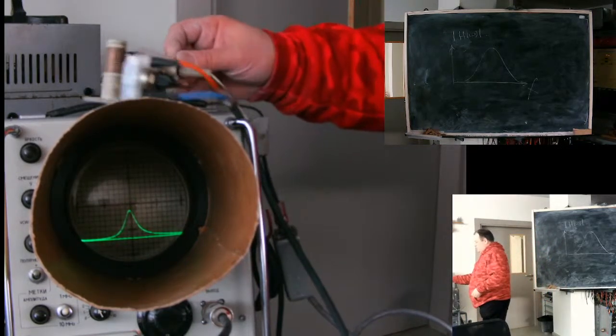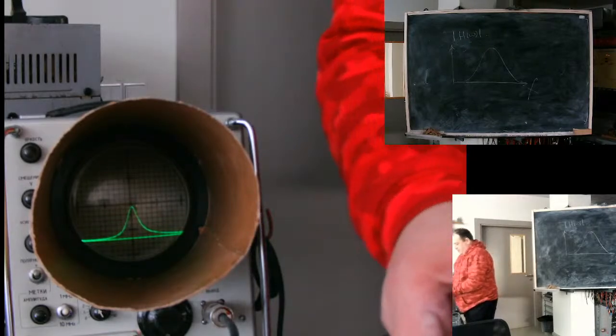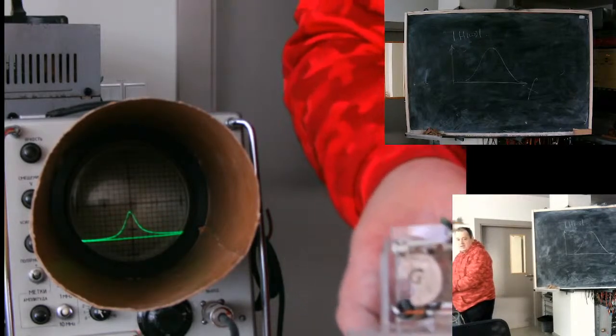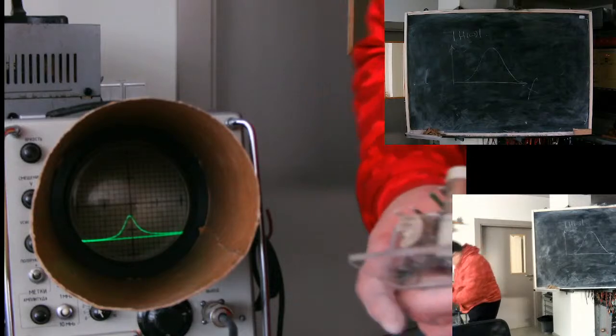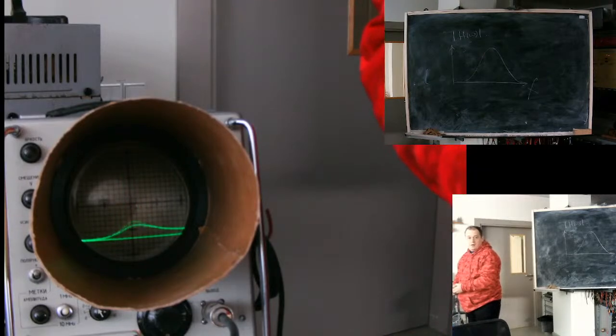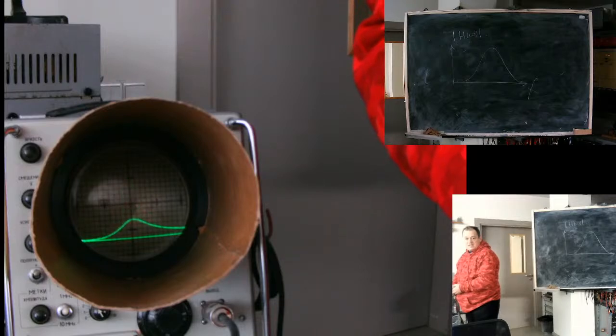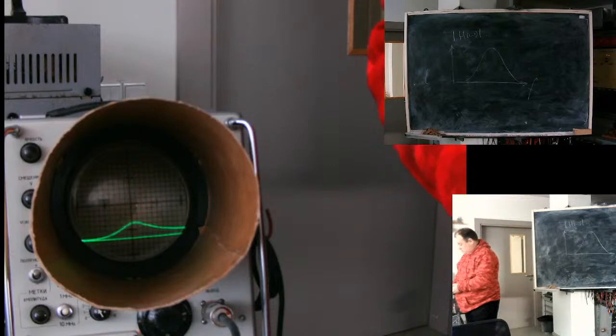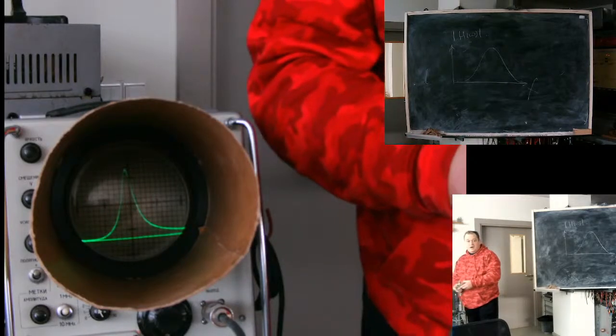Let's change something. What can I change? I can change the active resistance. One second, I'll switch scale. See what happens? Active resistance increases losses, diminishes quality Q, and the characteristic goes down. Meaning what? This network, its resonance, is not so good. You see? I'm increasing resistance.